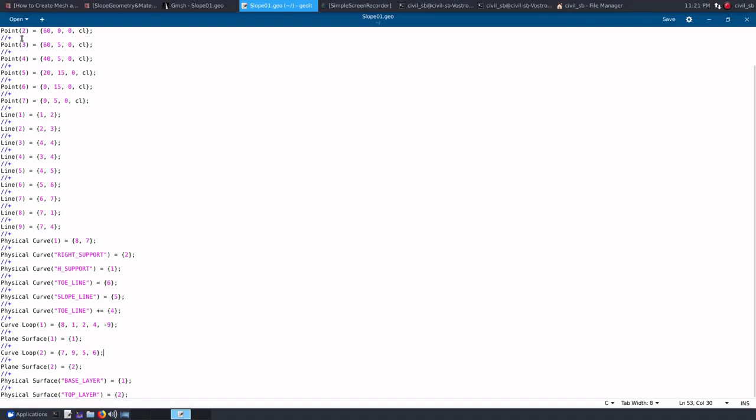Then the ID of that is put inside a parenthesis and then the equal sign, and in the curly brace we need to put the parameters that define that geometrical entity. Like line 1 was started from point 1 to 2, so this is my list of entities. Okay, so that way we can do the whole thing even in the text mode itself.